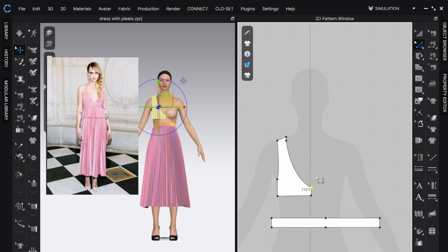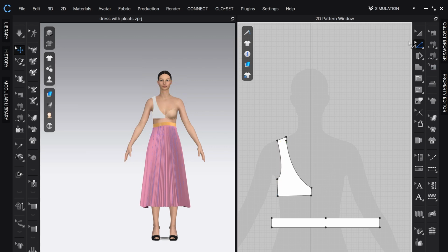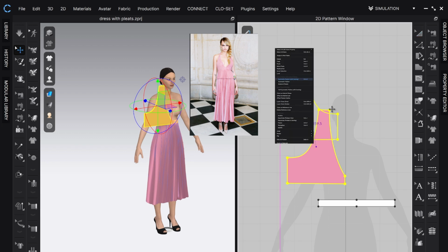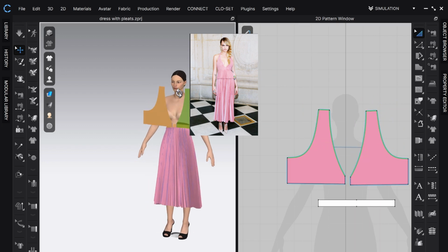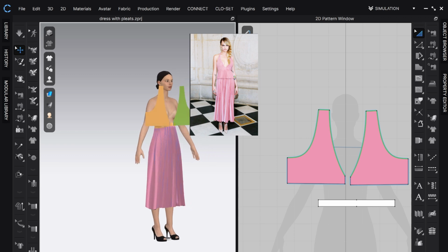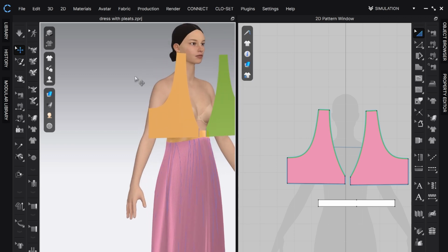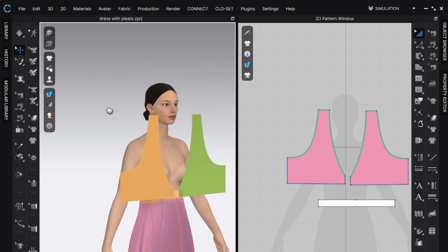And there is a lot of trial and error when you try to create a digital twin of an existing garment, trying to mimic real-life shape and flow of fabrics. Then select the pattern and Control D to paste symmetric pattern with sewing, or just click right to select this option. I will use the pin to avatar function when simulating in this case.